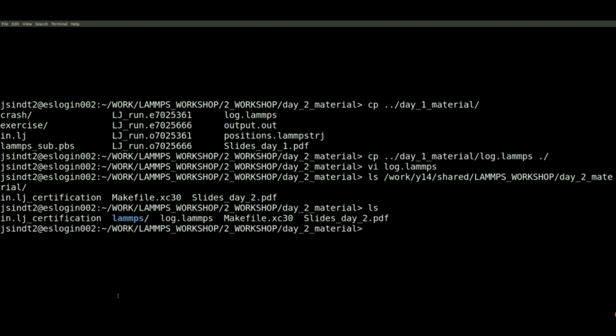And the first step to this is quite literally to clone the LAMMPS directory from Git. So git clone, you want to choose a stable branch. If you don't specify that you want the stable branch, you might end up with whatever the latest version is, which might or might not be entirely stable. Unless you're doing anything fancy or anything that LAMMPS developers are currently playing with, the other branches should be fine as well.